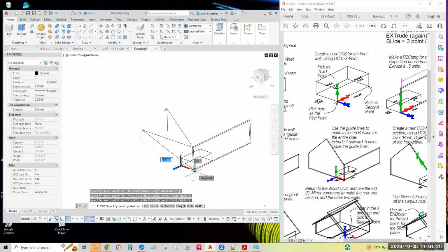I'm resting my cursor on it. Rest it a few seconds. Now, as soon as you change your view, you lose the acquisition. So without panning or zooming, you got straight edges or T-squares lined up straight down from the last point you picked and in line with the acquired point at the bottom of the screen there.